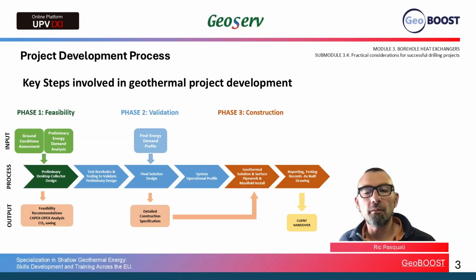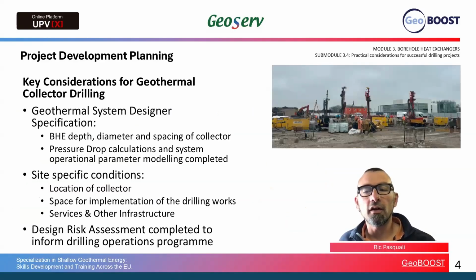In terms of looking at the drilling operations specifically, one would consider that in the last phase of development, which is the actual construction of the geothermal collector, the initial geothermal system design specification has already been completed. The system designer will have specified the borehole depths, the diameters, and the spacing at which a borehole heat exchanger collector would have to be installed.